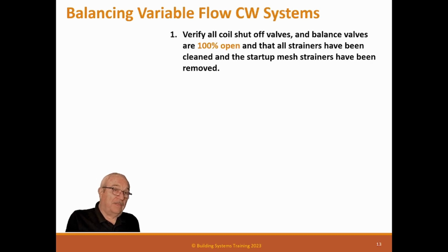All right, here we go. So how do you balance with chilled water flow? It's exactly like the airside system. We want the GPM of the pump to equal the GPM of all the connected coils so we can balance it like a constant volume system. That's what we're trying to do.